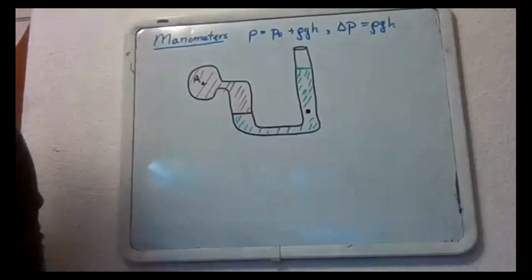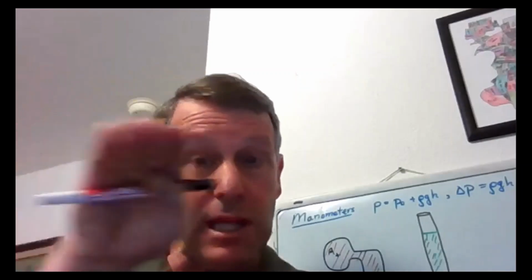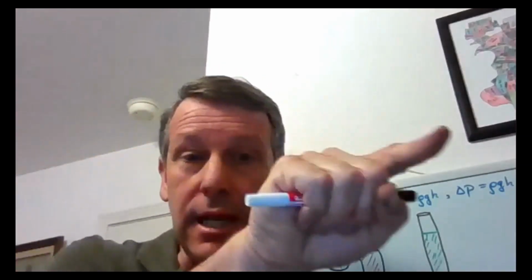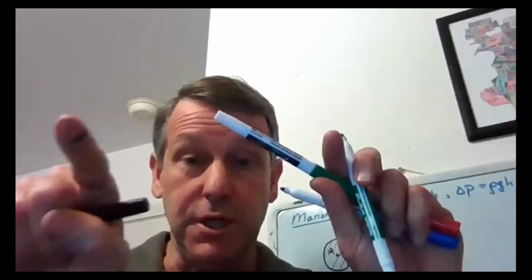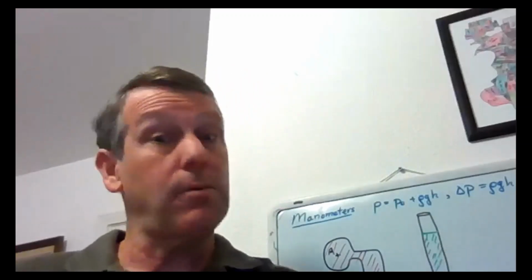So what I said last time, just really quickly, about manometry and doing these problems with fluid statics, so this is fluids at rest, is that what we can try to do with a problem is identify pressures that we know, and then work our way up or down by doing rho GH, keeping in mind that if we have a level within a uniform fluid, the pressure at any level is going to be constant. So the pressure here and the pressure here would be constant. And that usually allows us to take a look at a diagram, identify pressures, and get to the point where we can write an equation that allows us to solve for whatever we want.